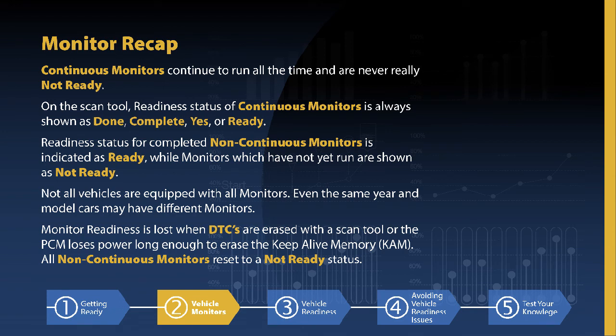As a reminder, continuous monitors run continuously and are never really not ready. A scan tool may read the readiness status of a CM as either done, complete, yes, or ready. Readiness status for completed non-continuous monitors is indicated as ready, while monitors which have not yet run are shown as not ready.